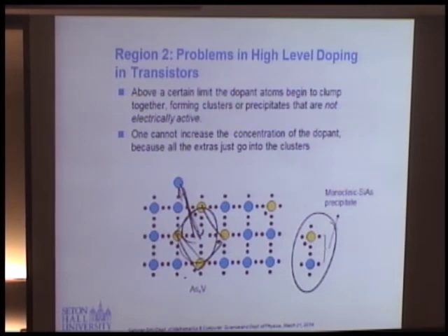So what do you do? If you heat it up a little, you get a supersaturated state, then quench it down, you have more arsenic in your sample, but it's still soluble. That's a metastable state. You can get this thing. And if you disrupt this, you can get all the precipitations. So we want to trap the arsenic in this metastable state. They do that by annealing.